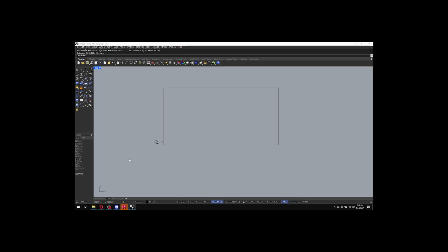Here, they have a nice little setting where, you can see down here, it says disabled. So that means off, essentially. I keep it off, but then at any point while I'm in a command, let's say we had this rectangle and I wanted to draw a circle on the corner. Well, if snaps are off, I don't know if I'm going to hit that corner exactly. But with it disabled, if I hold down Alt while I'm in the command, all of these turn on. I can then snap to that corner, let go of Alt, and I'm off the snaps. So it's a temporary on and off.